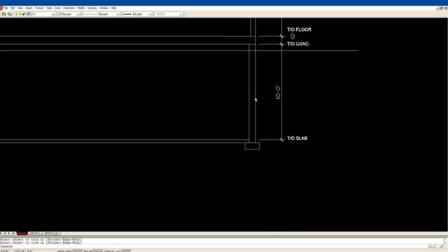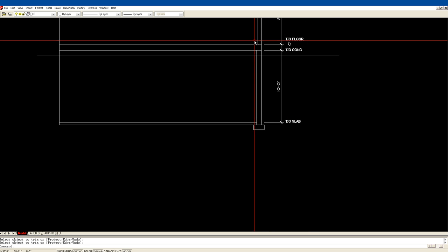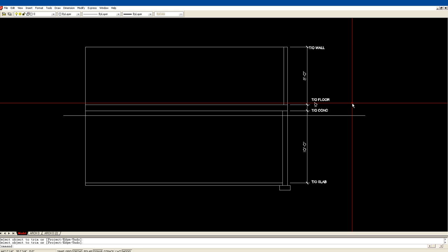So I have a footing, and when we finish off this cross section, we'll show 2 rows of rebar. Again, the engineer is going to change all of this. He's going to make his own drawing, but we're showing 10 feet to the bottom here. We're showing an 18-inch wide by 8 inches thick footing running around the whole building. Again, we'll show that fact, the continuous footing, in the foundation plan. Okay, we're showing the dirt. We're showing 8 inches below the top of concrete is where our grade is. And then we're showing the wall itself.